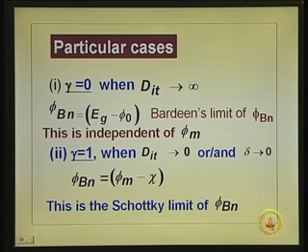Phi naught is actually the energy gap between the neutral level E naught and Ev. That depends upon the particular material, actually the surface condition of the material and the material itself. For gallium arsenide and silicon, it so turns out that phi naught is about 1/3 of Eg. If it is 1/3 of Eg, then this whole thing will become 2/3 of Eg. We will take a look at that further.